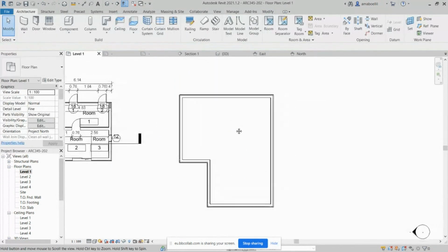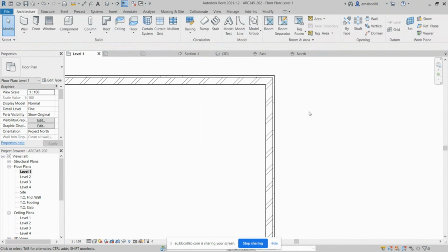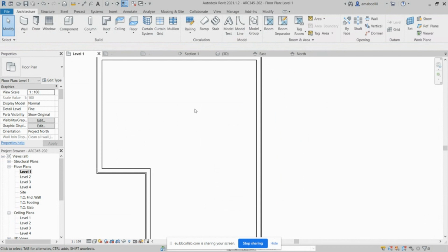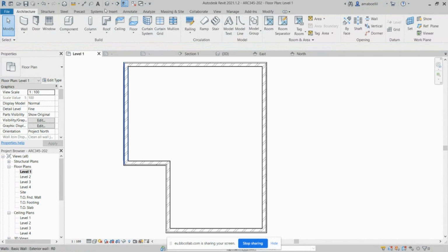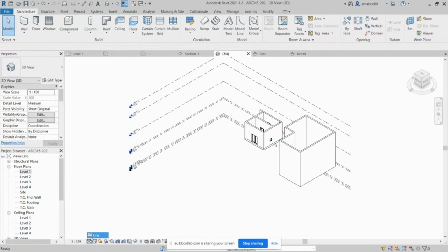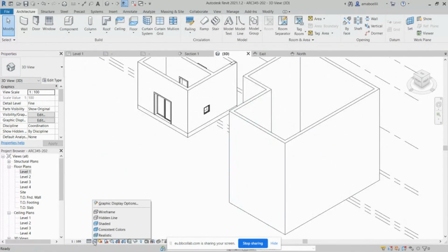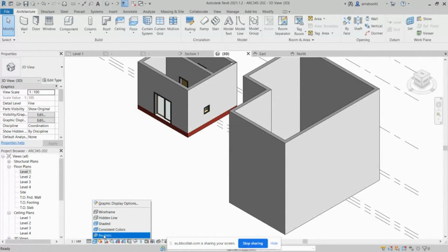You have to make sure of one more important thing, that the orientation of the walls is placed correctly, so that this faces the outside and this faces the inside. Sometimes when you draft, you'll find some of the walls are flipped, and then when you check the 3D and put high quality in it, you will see that the wall sometimes, regarding the pattern, is flipped. So let's make that. This is constrained, this is realistic a little bit, it will just take some time. But if you do that, you will see that the wall is not showed as flipped. You can flip it, you can still click the wall and adjust, especially if you have a pattern for the outside, it will show up directly rather than seeing it as a realistic view.